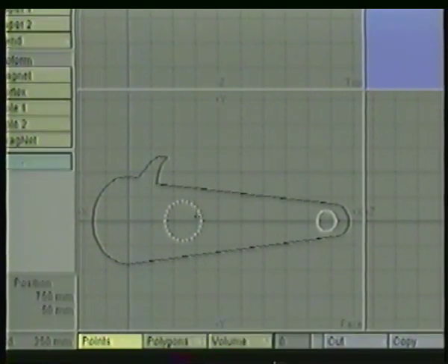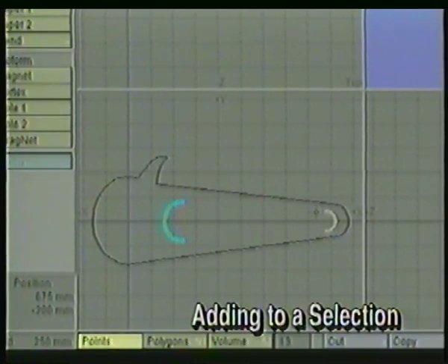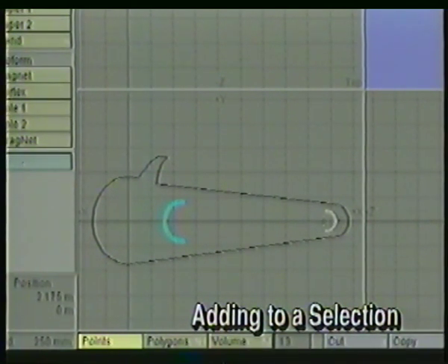and then go back to point mode so I can start selecting the inside points. I'll hit delete on the keyboard and I'll select the left side points and hit delete on the keyboard. And once again, I'll start selecting points in order. And I may need to zoom in here, so I have to let go of my mouse, which means to continue selecting points, I'll either use the middle mouse key or hold down the shift key.